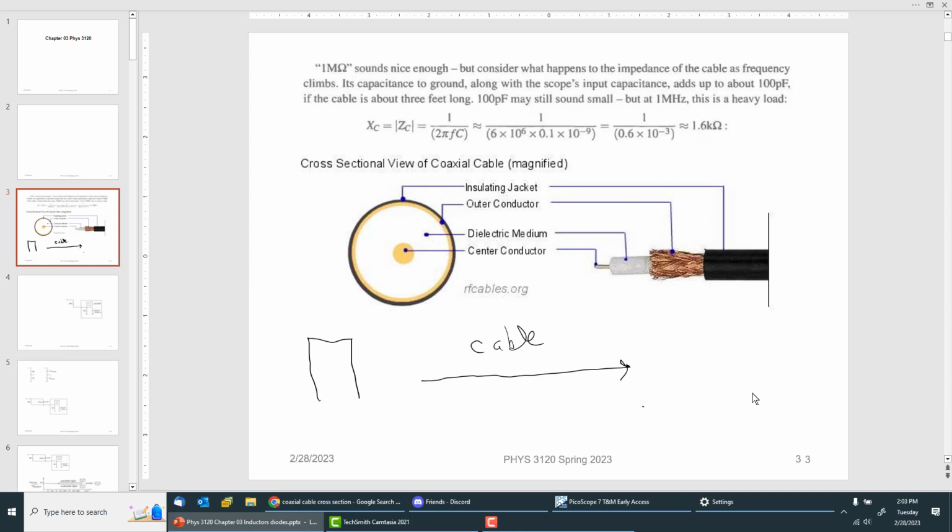But it tends to happen over long distances of coax that this pretty square wave you put in starts looking like this. Or that's pretty extreme because of the RC. You've got a rise time and a decay time. And the solution to this is to actually use wider coax cable. So the coax cables of your probes are quite small. You'll see up there some coax cable about 1/4 inch in diameter. That's actually called thin coax.